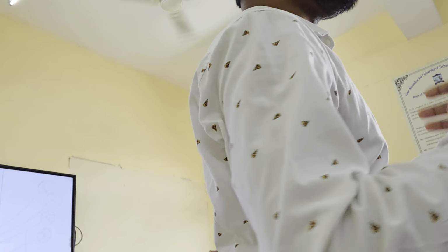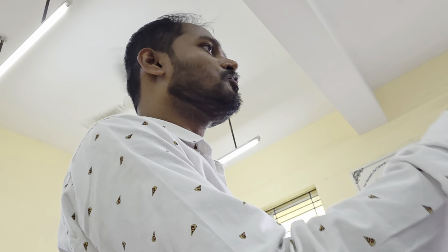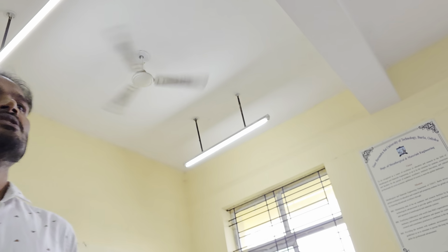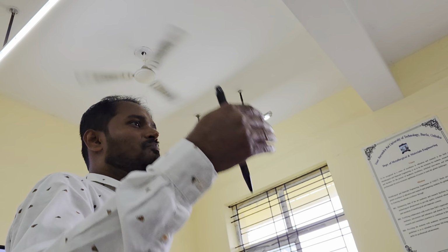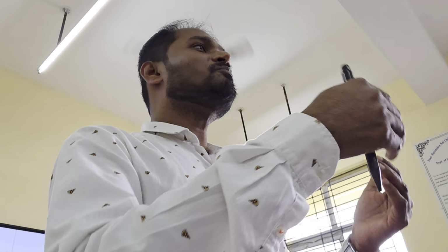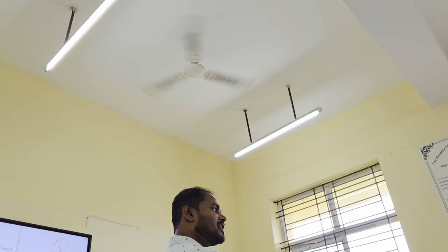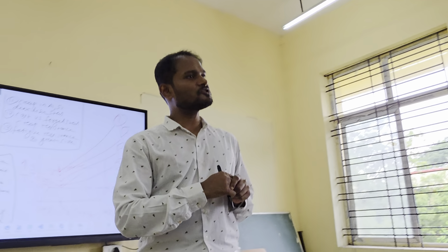That is one point. Second one is some force or pressure is required, because the lathe machine is moving to and fro, right? So if force applied is more or power consumption is more, that means poor machinability. Steel has poor machinability. Less power means good machinability. And the last one I told, chip may be continuous or discontinuous. If continuous chip, poor machinability. If discontinuous chip is forming, it is good machinability steel. So that is affected by grain size. Okay, you understood my point?